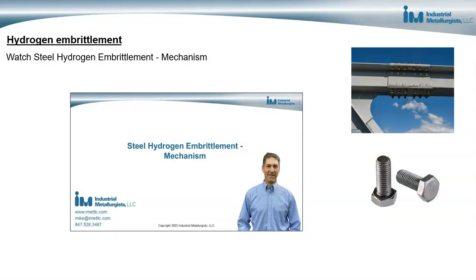And again, with hydrogen embrittlement, we are concerned about the failure of steel components due to the exposure to hydrogen that results in the components becoming brittle, losing ductility, and cracking and fracturing at stresses that are less than the metal's yield strength.